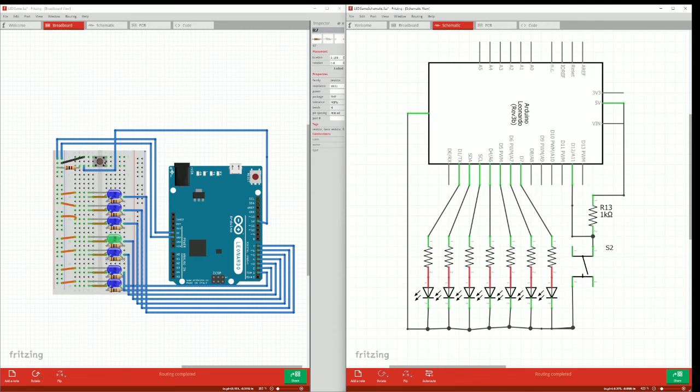Second thing is this button. This button or switch shorts the current so it completes the circuit, and current is sent through this little miniature circuit right here. The change in current is detected by port number 12, through this wire I'm clicking on. The change in current that's being detected sets off all of the code, which is the blinking LEDs and whatnot.